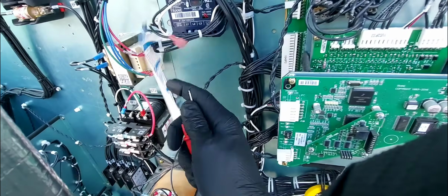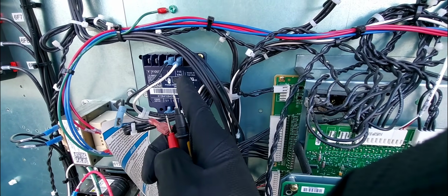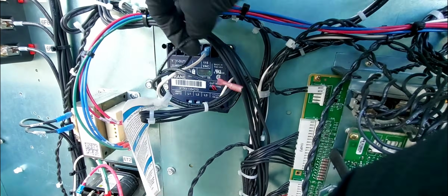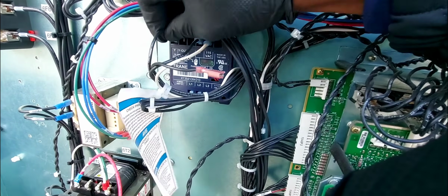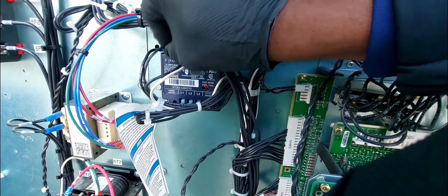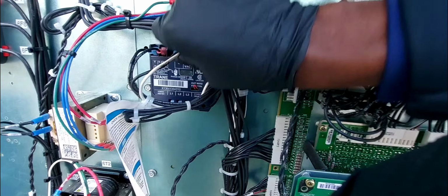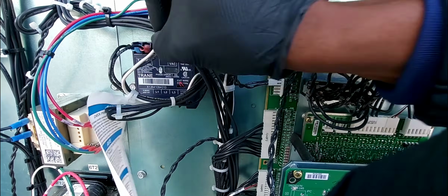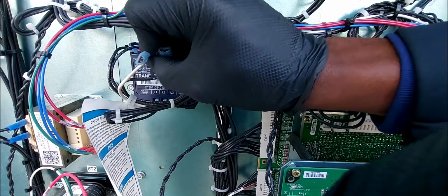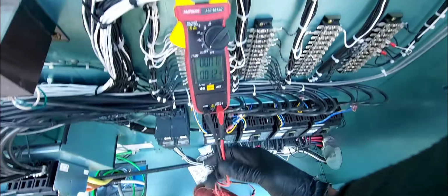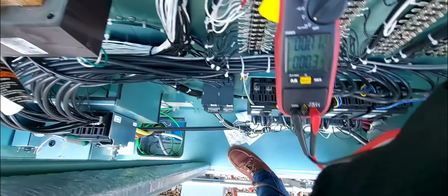So I'm going to go ahead now and see what's going on with my power for this phase monitor. I put these wires back. I don't want to get them crisscrossed, even though if you do get them crisscrossed, you can just look at the schematic and verify. And the Trane schematic is not really a user-friendly schematic. All right, so then I'm going to pull those off and check for power, which I'm pretty sure there's no power. All right, I'm going to go to AC. Boom,